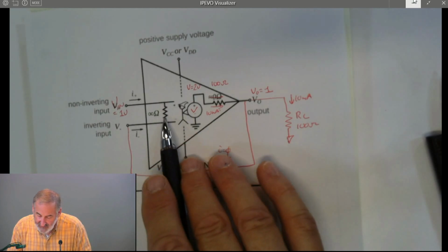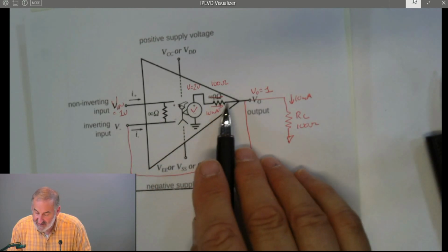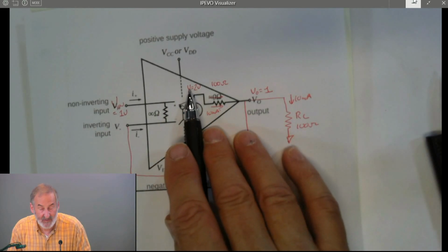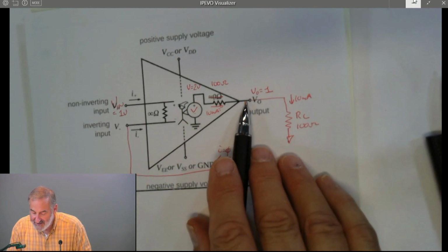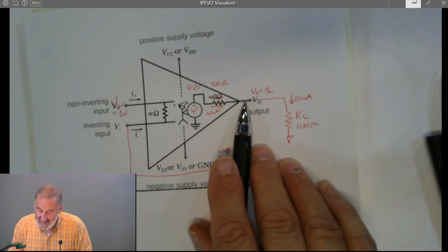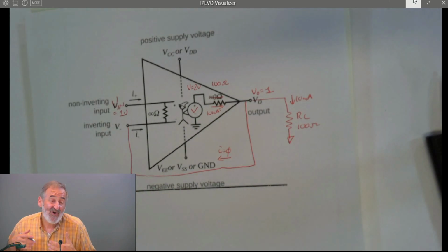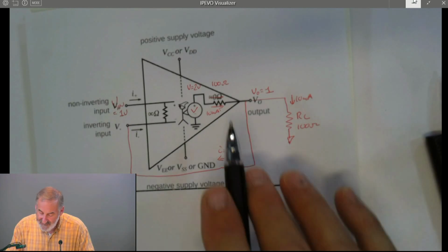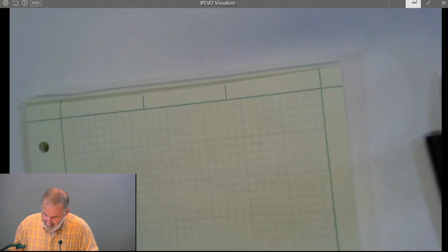So there's a little bit of voltage difference here. And that voltage difference has to be a little bigger if we need 2 volts here when there's current flowing rather than 1 volt. So there's a little bit of change in this voltage. But once again, this resistance is effectively divided by a number near A. And so even if it's 100 ohms, once we divide it by 200,000, we're in the milliohm range. So feedback causes this output impedance to effectively be 0.